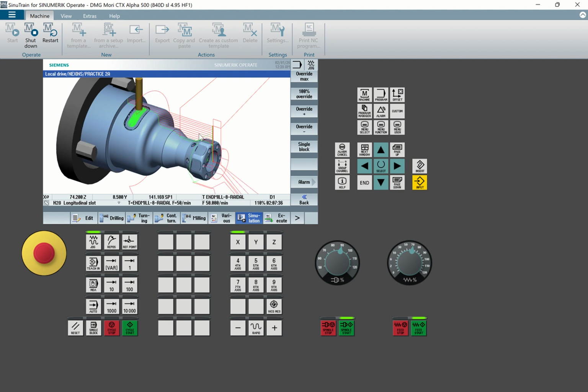Sheet Y is like you're doing facing on the Y axis, but this I'm doing milling, across or along the surface of Y. So this is a turn-mill, so it has X, Y, and Z axis, but the main axis is X and Z. So Y is the auxiliary axis, as you can see how it is doing it. So this one now uses the Y axis at these cuts.